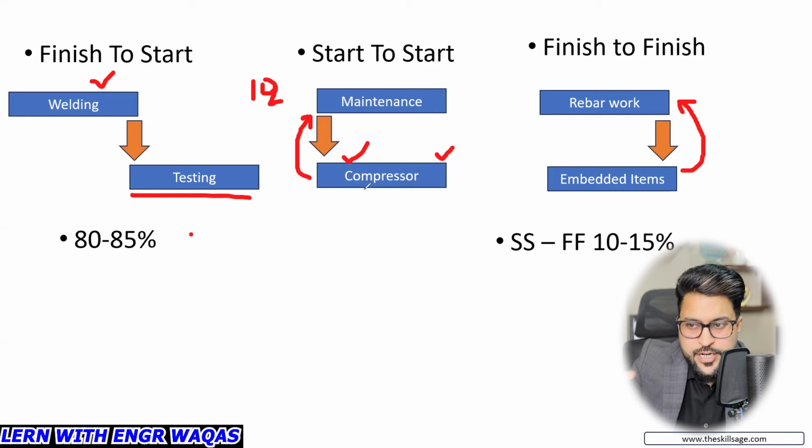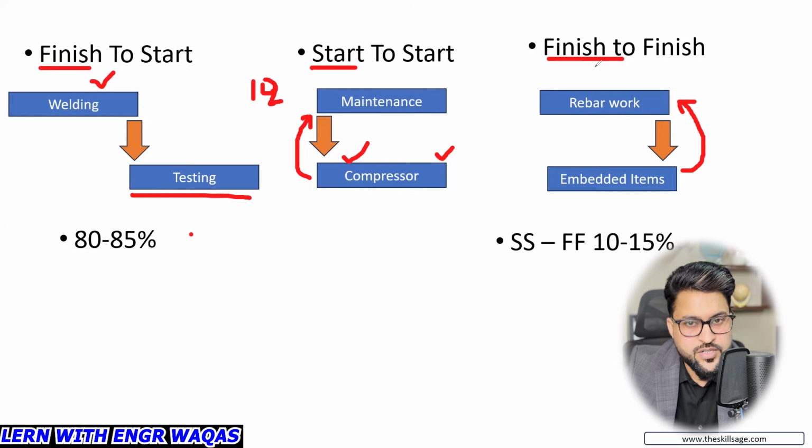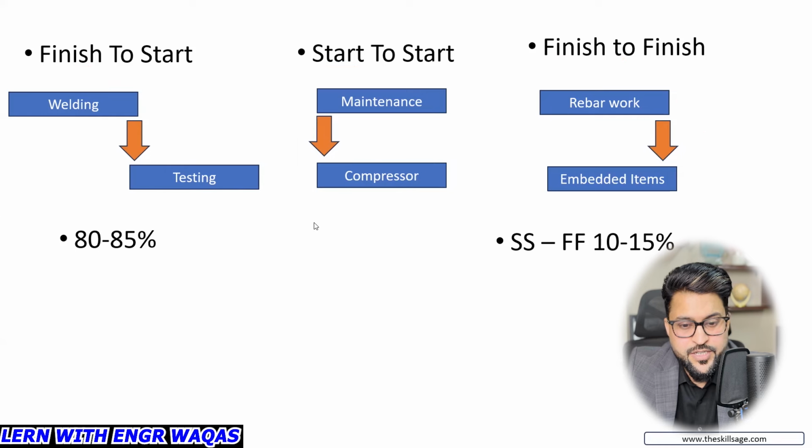A successor activity is usually where the arrow is pointing its head, and the tail of the arrow is connecting with the predecessor activity. That is a usual perception and pattern you can identify easily when you see your bar chart area. You understand? The second most important point: a successor activity is always depending on the predecessor activity status. If it is a finish to start relationship, this is the predecessor status. You understand? So it is very important to understand which activity is predecessor and which activity is successor. Okay. And from here I will be sharing how to do these things.